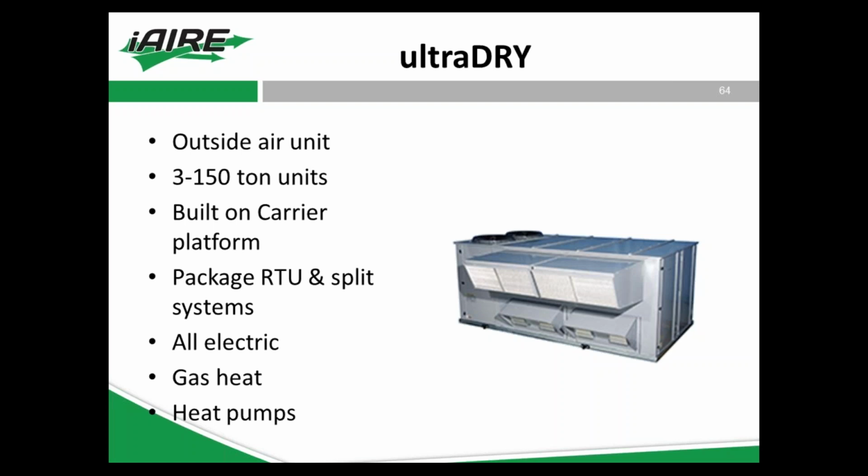They basically get stripped down and rebuilt as 100% outdoor air units. And you'll see, again, we can do all electric, we can do gas heat, we can do heat pump systems. They also do packaged split systems. Well, they do packaged RTUs, split systems, water source heat pumps. Just about anything Carrier can also be iAIRE.